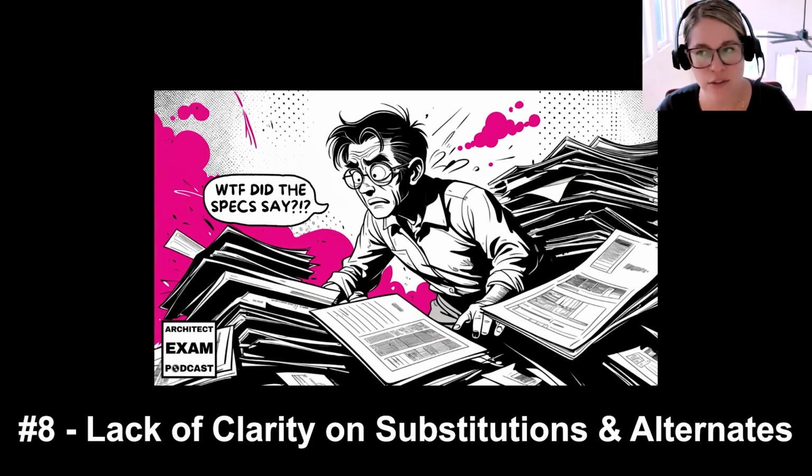This is when you see those famous words in specifications, "or approved equal." Okay, that's kind of open-ended. Without defining what an approved substitution or an approved alternate is on a product, that "or approved equal" really leaves it open for interpretation to the reader. And I feel that by doing that, we are definitely asking for trouble. So contractors will naturally propose less expensive alternates if they're given that type of language. And without clear criteria, it's often hard for them to evaluate what the actual intention was of that product.